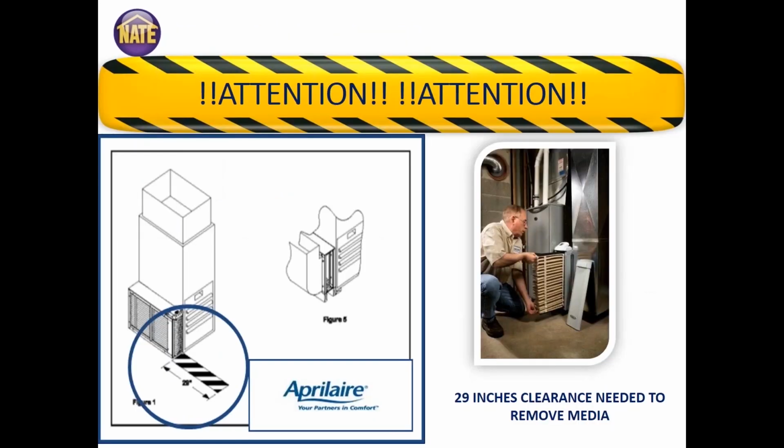This is true with any of our air cleaners. I just want to make sure as you're planning out where it's going to go, make sure you've got sufficient distance to pull that filter media out. I've seen more than a few jobs where they found a great place for the cabinet, and when it comes time a year later to change that filter out, they can get the door off no problem, but they have a bit of a challenge getting that filter out. There could be something as simple as a natural gas black pipe stub there, or a pipe, or what have you. It's just a little bit too close or a little bit in the way.